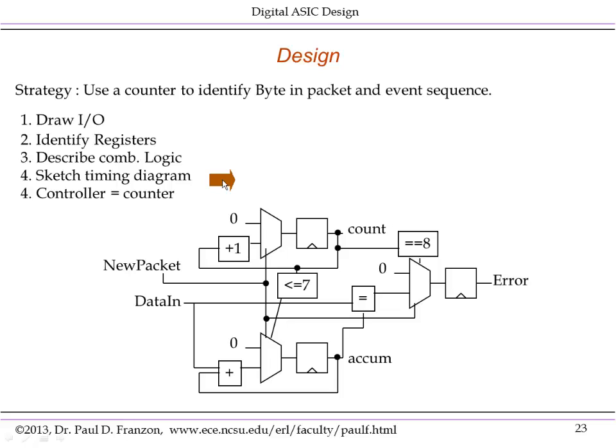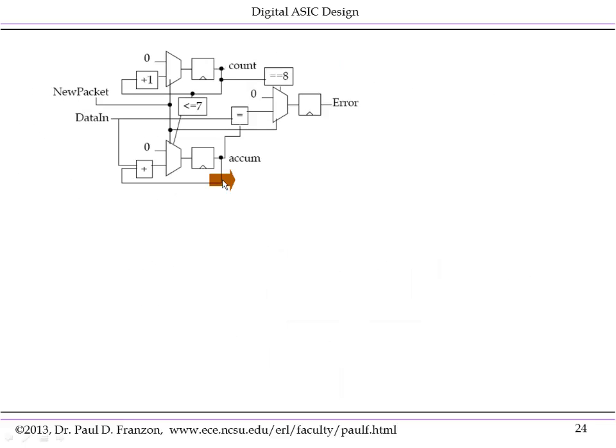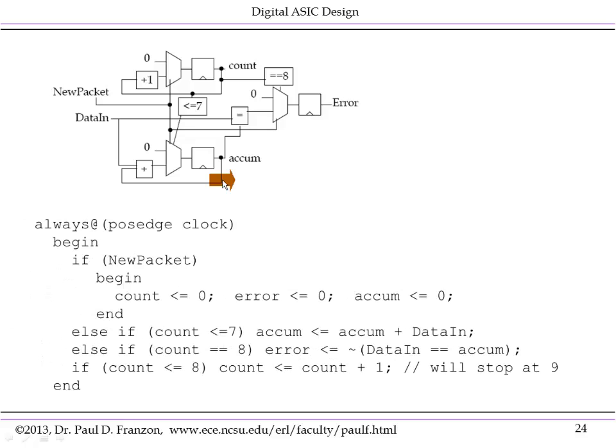We then translate this design into code. And here is that translation. I've lumped all the flip-flops into one procedural block. Of course, by using non-blocking assignment, this is quite safe to do. So what I'm doing here, if new packet is high, I'm clearing all my registers.